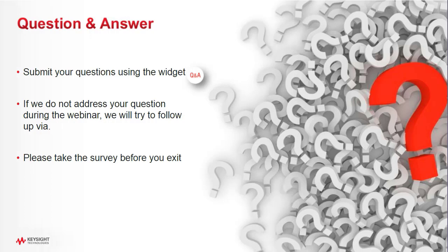Yeah, that's another very interesting question. If you remember the design project I just demonstrated that has a TX AMI that generated PAM4 signals. However, in the middle there is a redriver, which is actually pointing to another AMI model. So if you want to adjust any power level or signal level before it hits the optical channel, you should be able to handle those variations through the AMI model.